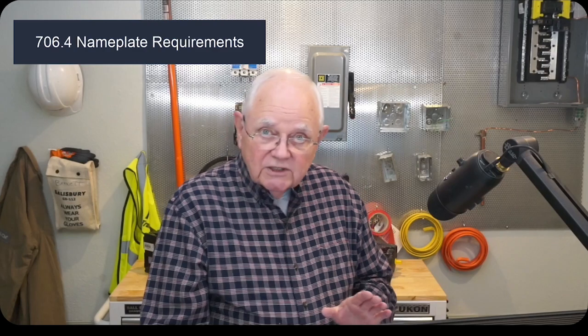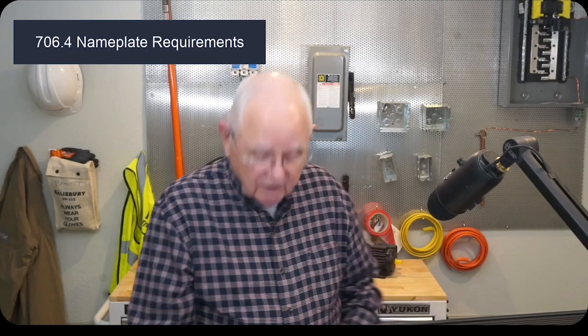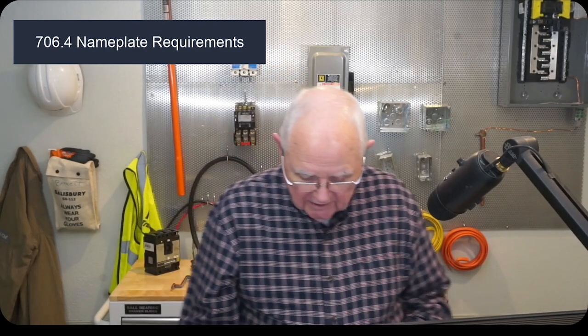There's required to be a nameplate, it talks about in 706.4, for the energy storage system. So we can look on that nameplate because you think about it, what are we interested in? We're interested in input voltages, output voltages. We're interested in current ratings as well because we can use that current rating in order to size the ampacity of the conductors. So nameplates are required to be there, and 706.4 then lists all the requirements on the nameplate. We talked about it all has to be listed, and